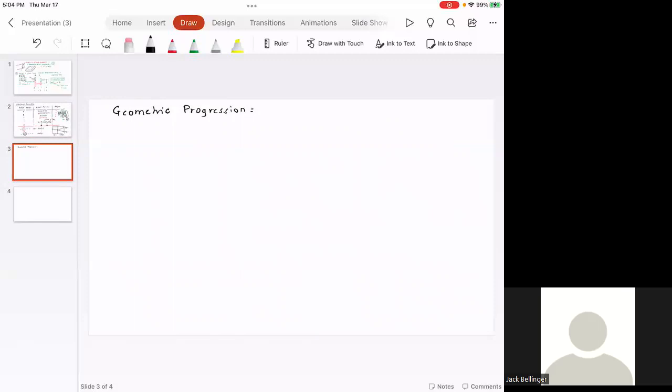So what you have is you have actuators. Believe it or not, those actuators are actuated using the differential pressure between the different sides of the actuators, and the gears get shifted. That's why the transmission oil is usually at a high pressure when the transmission is running, and basically that does a lot of work when the gears get shifted. So for geometric progression, the procedure for the stage design is the same whether you design an automatic transmission or a manual transmission.